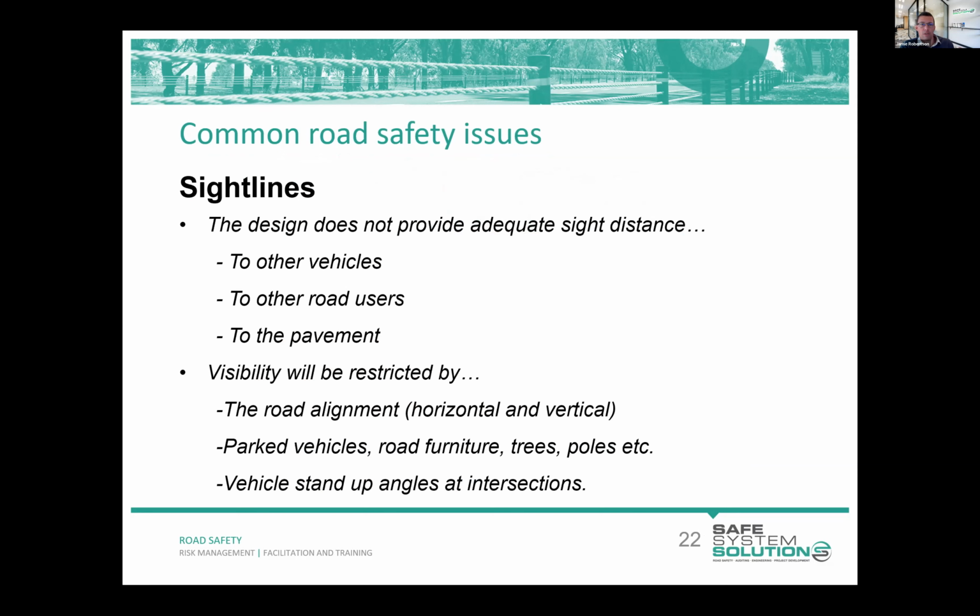Another common safety issue relates to sight lines. The intention of sightline requirements is to provide enough time and space between different road users to allow them to take appropriate action. So we have sight distance requirements for drivers of vehicles, for pedestrians.